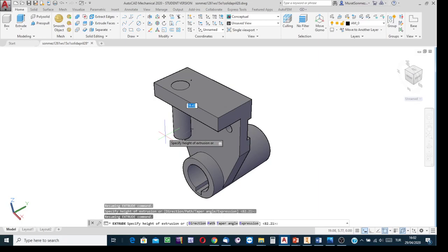But here in AutoCAD, while creating this cylinder, it is for cutting the material to create the hole. Do not extend it further, because if it interferes with another solid feature, then when you subtract, that part will also be subtracted. So the length of the cylinder should be in this order. Do not extend it further.